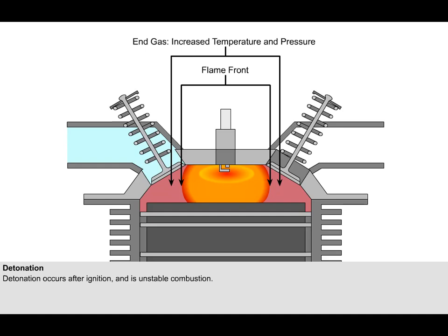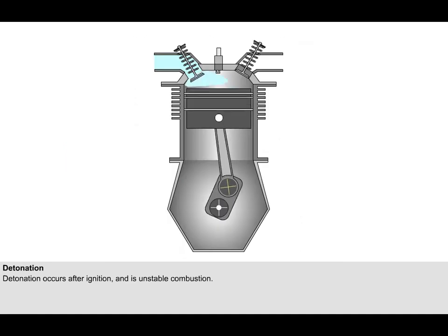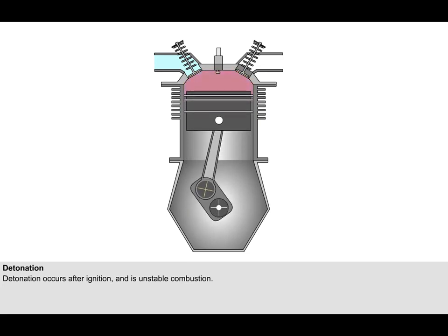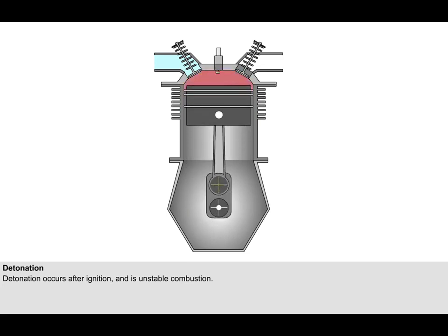In addition, the burnt gases have expanded, so the end gas is subjected to an increasing pressure and therefore its temperature increases further. If there is sufficient pressure and heat available to bring all the end gas to the point of combustion at the same instant, it will explode or detonate. The flame rate will increase to 1,000 feet per second, with a degree of violence which will depend on the amount of end gas that remains.